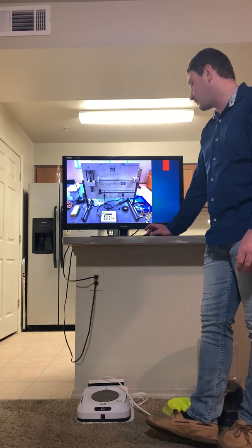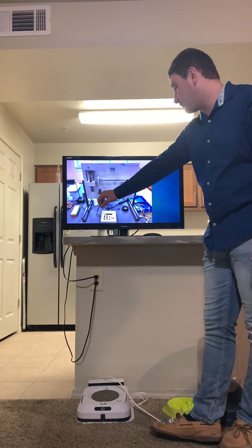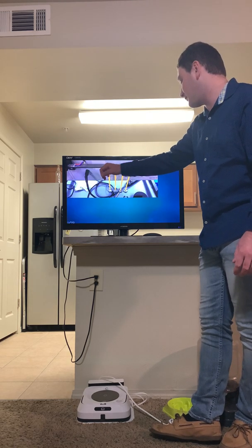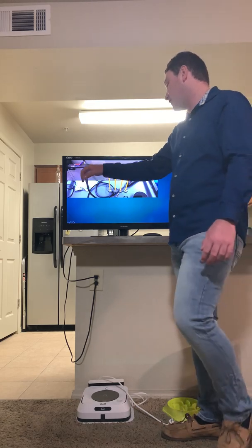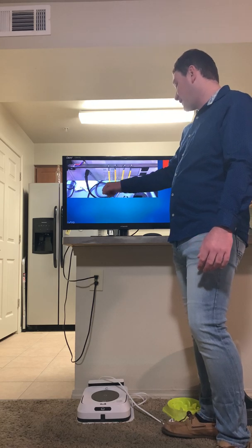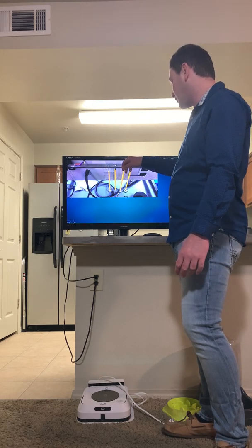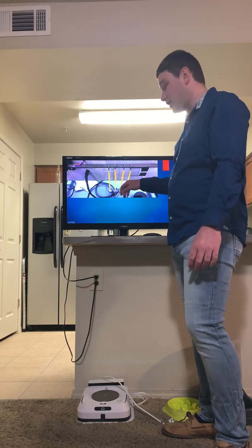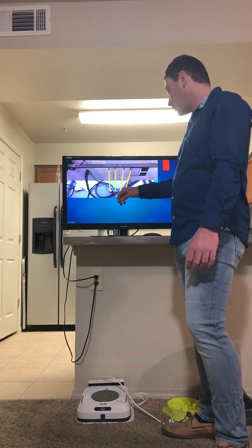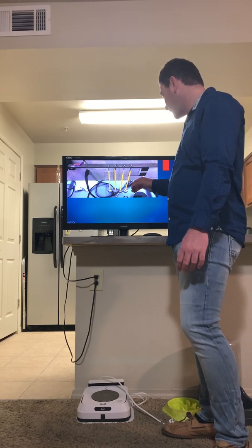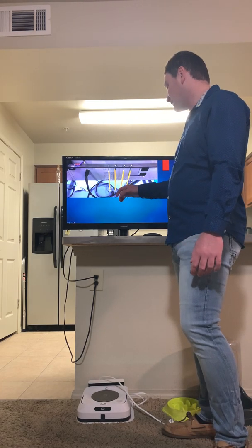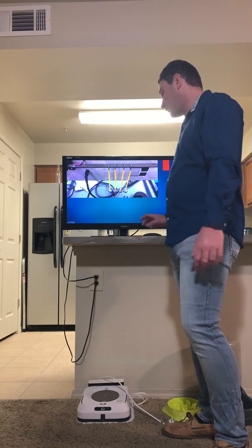So this was the equipment that we used. This was the cantilever beam, and in the next picture is all the equipment, but in this picture, this is where the loads are applied to the cantilever beam. Here we have just 4, and there are certain measurements up here so you can record where each weight is, and then we took measurements and recordings at 4, at 5, and then with 6 points of interest where there were weights, along the cantilever beam. So that's the equipment that we used.